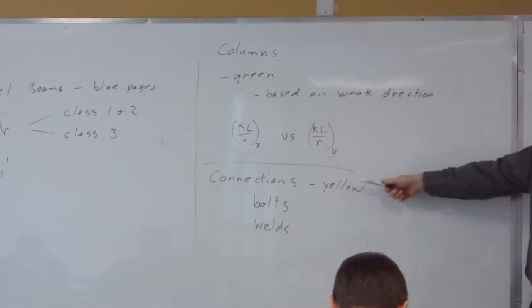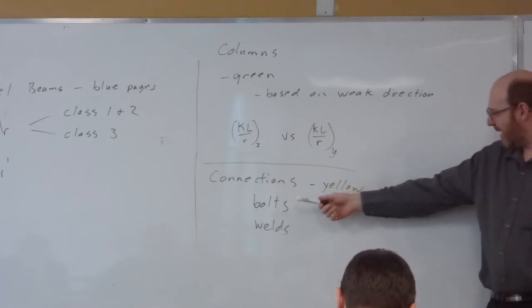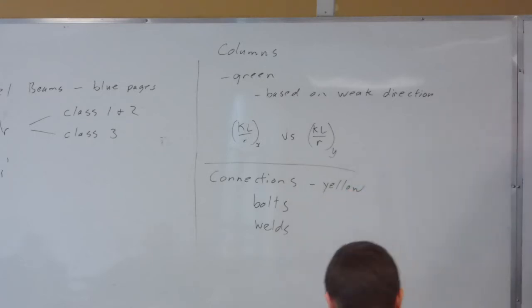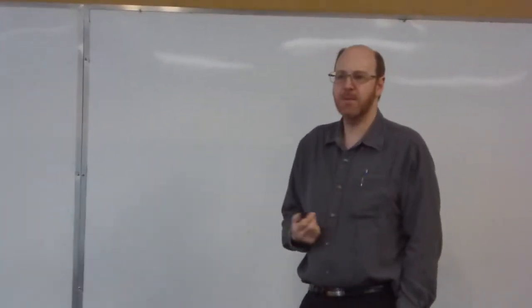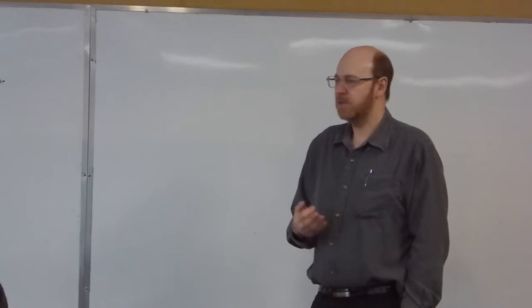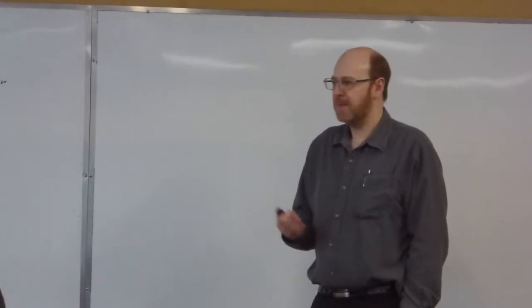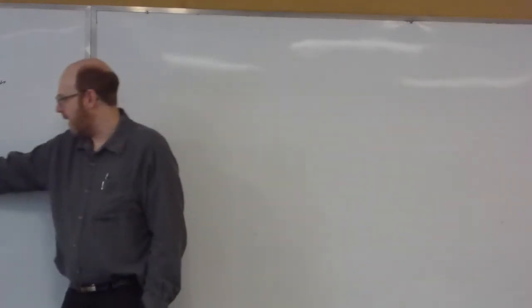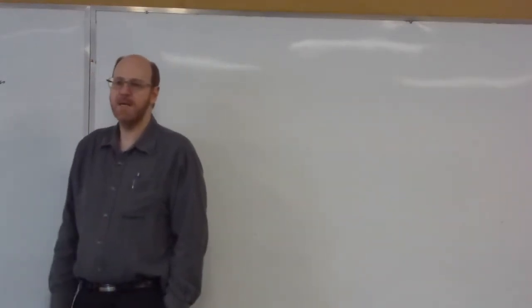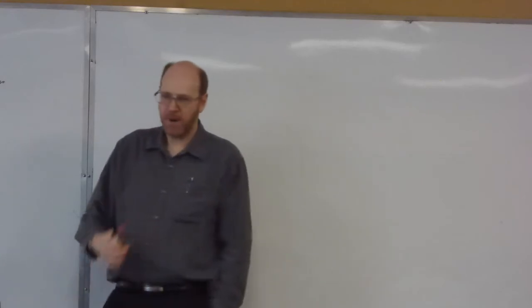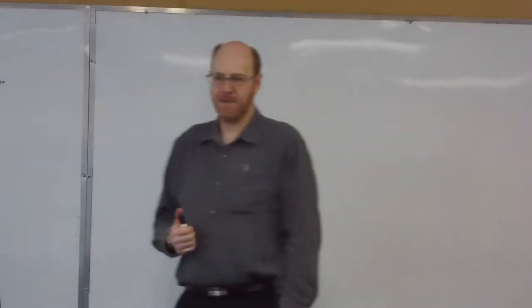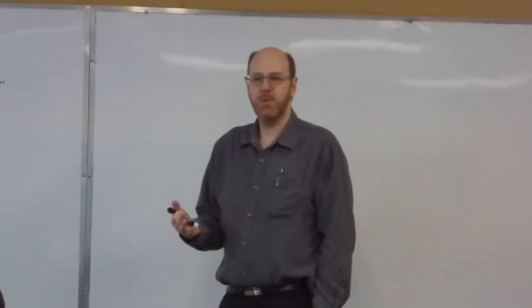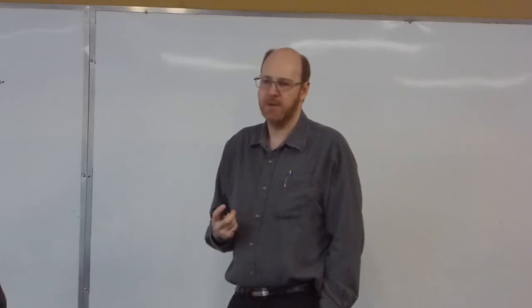So with a bolted connection, we're looking at a shear resistance. So we're just looking at the number of shear planes, right? So we looked at single shear versus double shear. And each bolt is going to have a particular shear resistance. So there were several different grades of bolts, an A325 or an A490. And we talked about threads intercepted or threads excluded within that shear plane, but it's a basic shear connection.